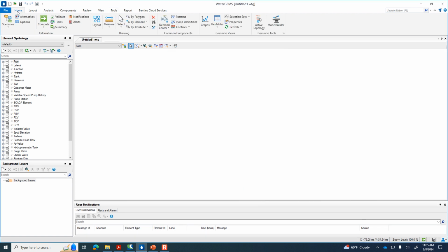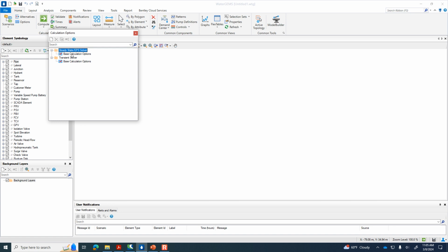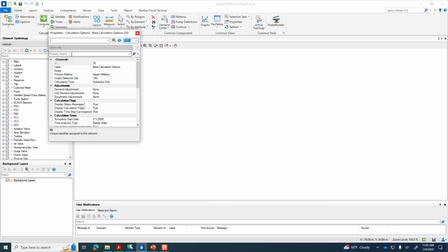And then the other thing I would check at the beginning, anytime I start a new project, is to make sure that I'm on Darcy-Weisbach. So that's under the Home tab, Options, Base Calculation Options, double-click that. It's on Hazen-Williams, and so I'd switch it over to Darcy-Weisbach.